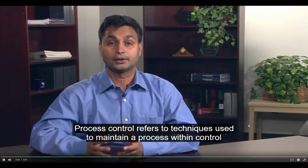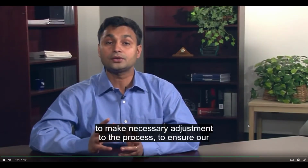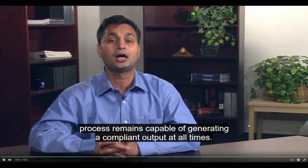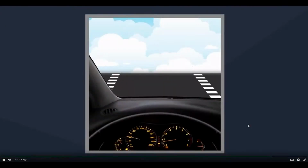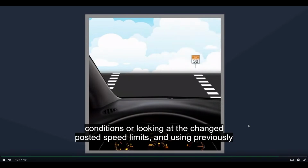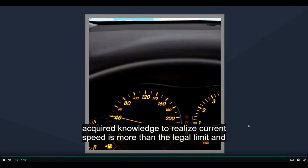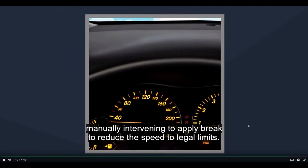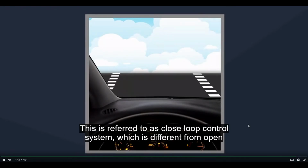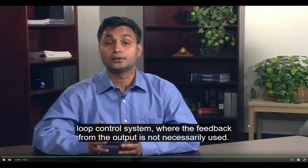Process control refers to techniques used to maintain a process within control at all times by using feedback from the output to make necessary adjustment to the process to ensure a process remains capable of generating a compliant output at all times. In the car example, this could be human eyes looking at the changed road conditions or looking at the changed posted speed limits and using previously acquired knowledge to realize current speed is more than the legal limit and manually intervening to apply brake to reduce the speed to legal limits. This is referred to as closed-loop control system, which is different from open-loop control system where the feedback from the output is not necessarily used.